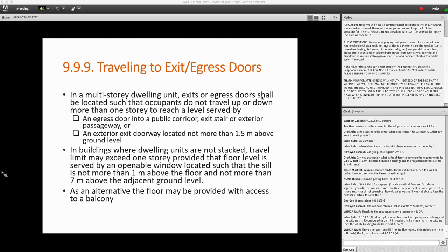So unless you have multiple dwelling units, meaning you have multiple suites in a floor area in a building where you have to comply with the requirements for instance, egress doors opening into a public corridor or having an exterior exit doorway from each dwelling unit, then the provisions on there are not applicable. I believe this answers your question.